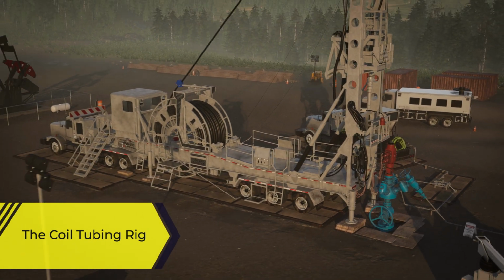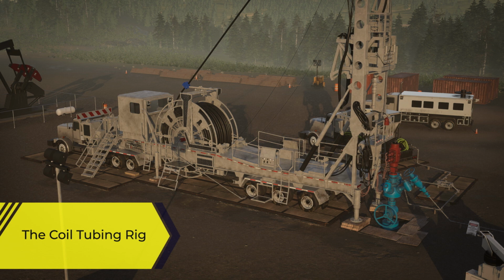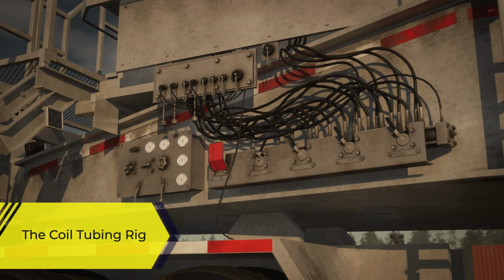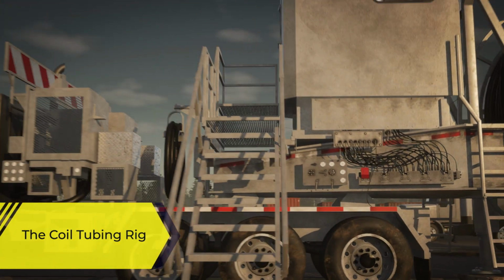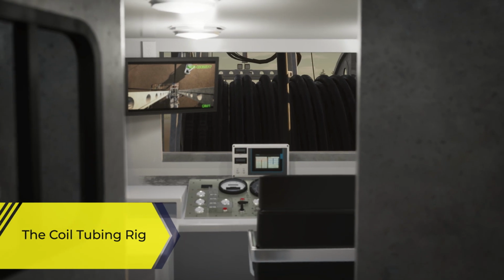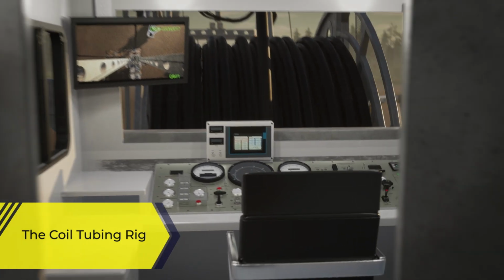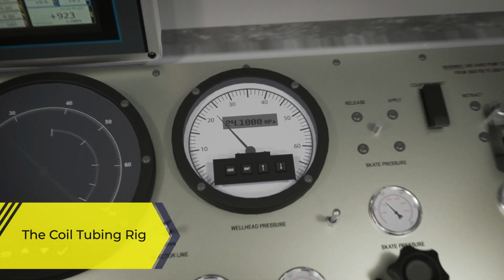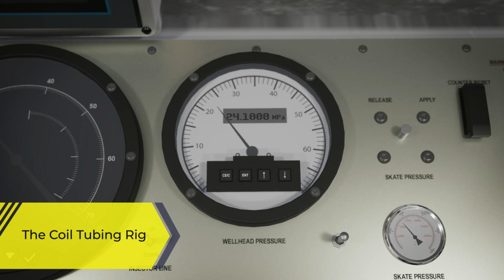The rig is equipped with 2 BOP controls. The first is located on the side of the rig, and the second is located in the cab of the rig. A variety of controls are in the operator cab that aren't available on the outside of the cab, including panels that display the pressure at the BOP.